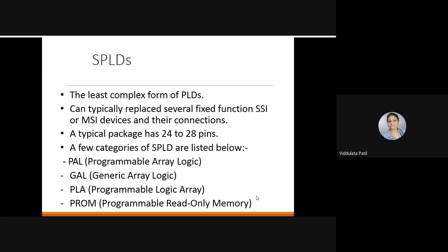This is one package that has 24 to 28 pins, and a few categories of SPLDs are listed: one is the PAL, that is programmable array logic. Then another type, that is GAL, that is generic array logic. Then PLA, that is programmable logic array, and PROM, that is programmable read only memory. So these are the different categories of SPLDs.